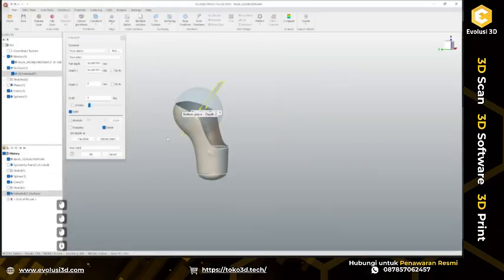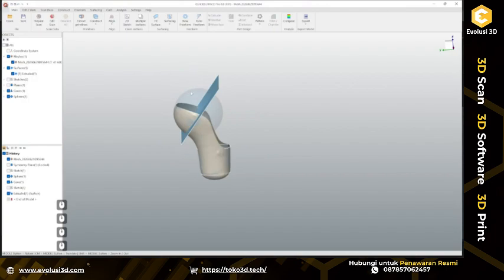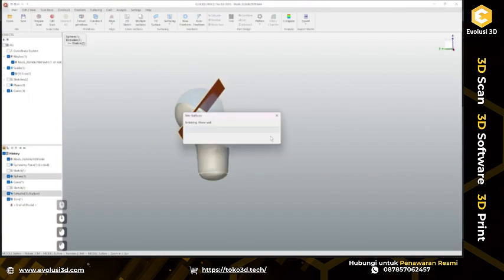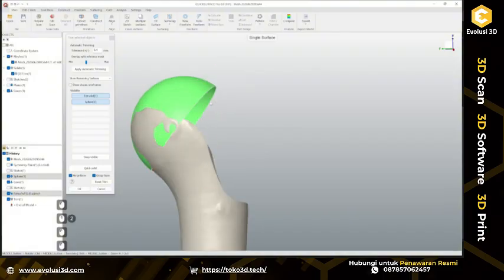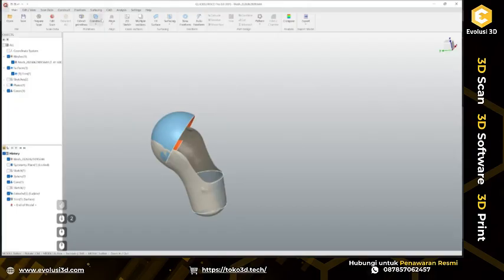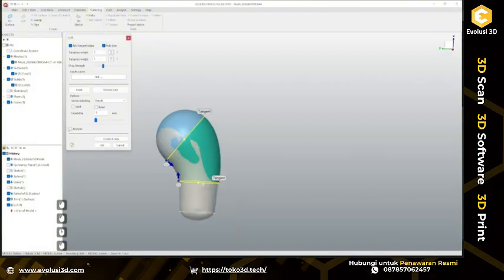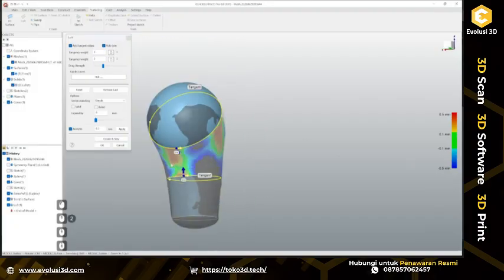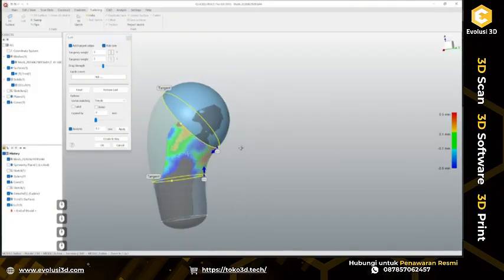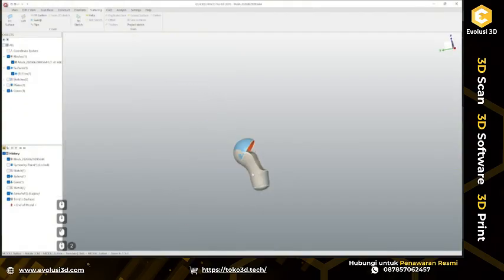Let's extend this line, extrude it to create a surface. Let's just trim these two like this. Okay, so now I have two surface bodies, and now I want to create a loft in between them like this. Okay, and let's see the result. To be honest, it's not that bad. So definitely this approach could be used here.